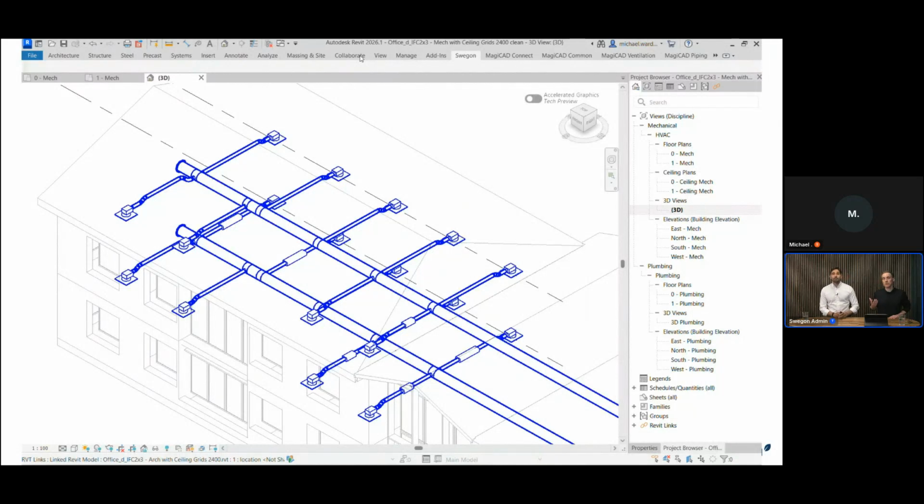And again, just to repeat, did you say that first we do the calculation of the big sound source, like the air handling unit? Exactly. Place a silencer there, then do a recalculation and see if we meet the demands. Then start the placing and do a recalculation. Exactly. See if we need to change. It's always more efficient to treat the sound at the source, and then run through the system and treat the sound closer to the receiver side after that.